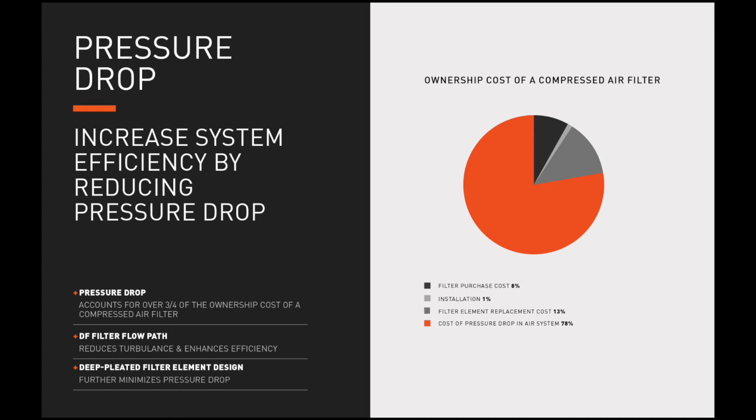Excessive pressure drop results in poor system performance and excessive energy consumption. Minimizing differentials in all parts of the system is an important part of an air system's efficient operation. The highest pressure drops in a system are usually found at the point of use: leaks in piping and hoses, and FRLs, filters, regulators, and lubricators.